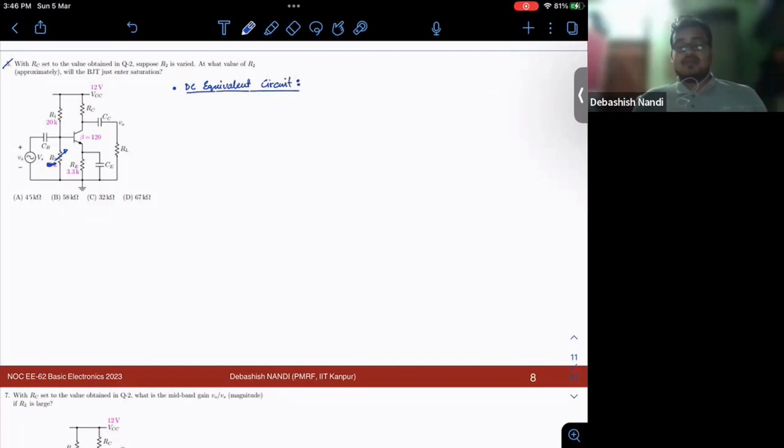Before starting that, why am I doing DC analysis, right? DC analysis is being done here because I assume this VS to be very small compared to my applied bias. Okay, so it cannot shift my operating point or the Q point. If my VS is comparatively higher, then my analysis will change, and I cannot simply use the DC analysis. I have to consider my VS also. This is particularly important in the boundary regions of active, forward active and saturation, also forward active or cutoff, right?